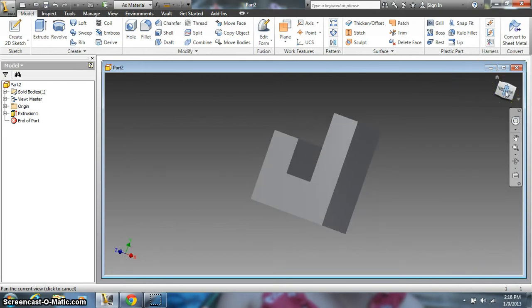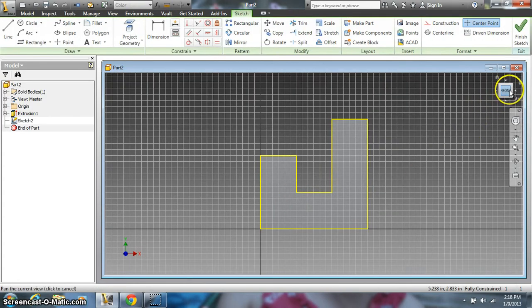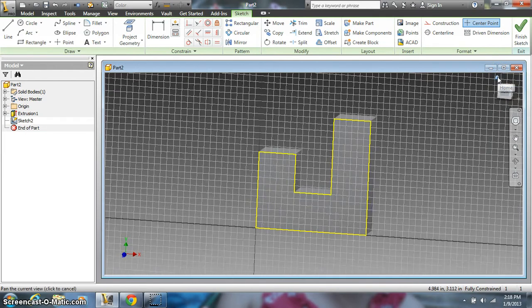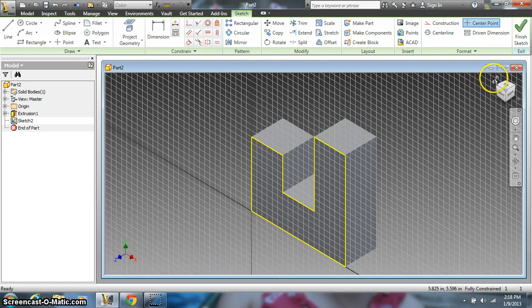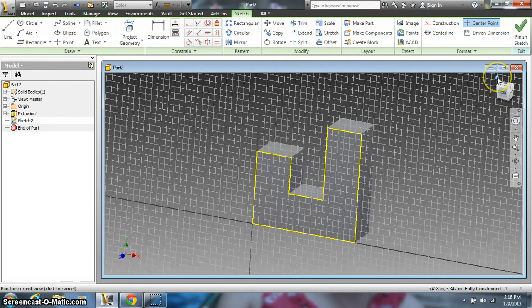We want to add another sketch onto this and make sure that we are able to add another block. To do that, we have a solid model here. We want to create a 2D sketch. This is like throwing a piece of paper onto the block and allowing us to sketch. We can pick any surface we want to put that on. I want to put it on this front face. Notice when I do that, I go to my View Cube area and front shows up. I can draw in isometric if I want. That's fine. Notice the graph paper turns on an angle as well, or I can draw flat. You can get used to doing either one.